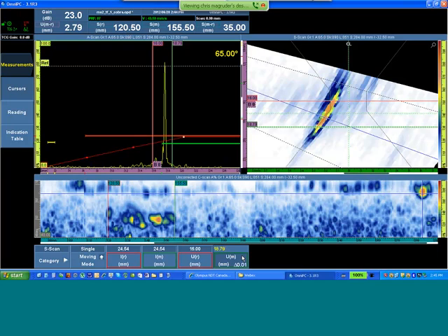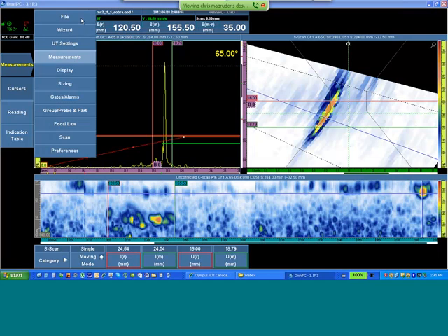Again, we typically always oversize defects, so we want to be conservative. Based on your weld bevel, your destructive testing and your procedure, somewhere in about a 3 to 6 dB drop, or in a rapid drop visualization of the flaw, you can arrive at a very tight specification. We would expect a 0.5 millimeter to 1 millimeter sizing accuracy in these types of techniques. Moving on to the next data file.